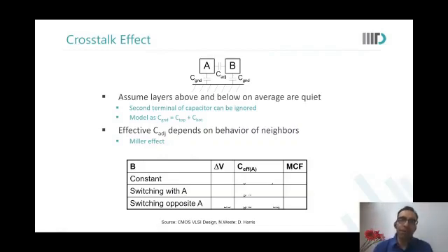Yes. Meher? Yeah, so just to clarify, the difference between lumped and distributed is that for every turn of the wire, we will associate it with a resistance and a capacitance. But what lumped does is it models the same between two nodes. So that diagram you were showing, it was taking all those turns and curves and modeling it as one resistance and one capacitance. Yes, that's lumped.